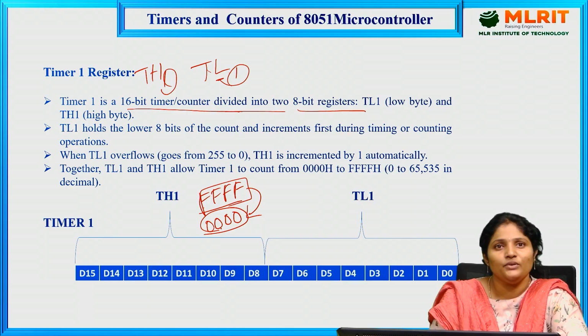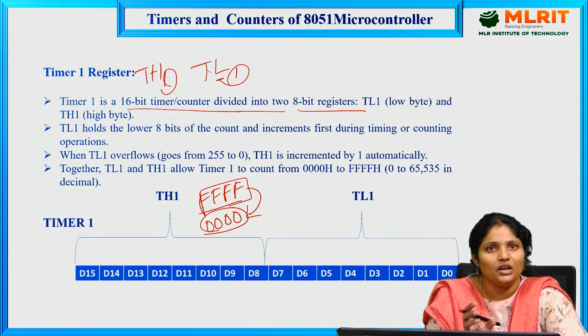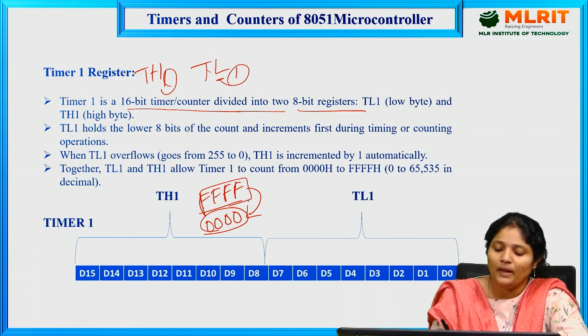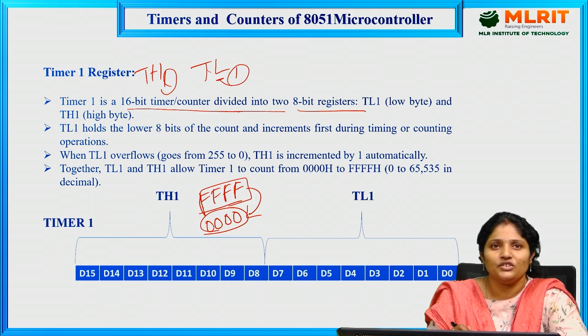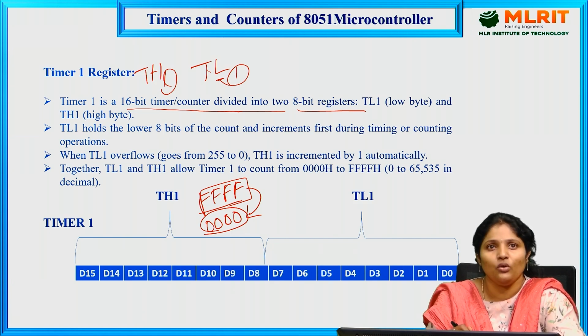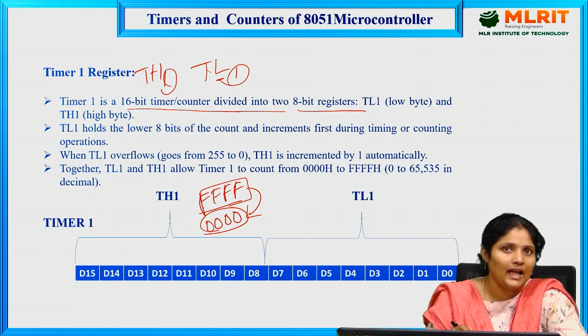When we are using counters also, if a 10-bit counter is there, it will count until 10, then next it will get back to the 0th location, the 0th count. Likewise, if it rolls back to the minimum value of that particular register, this is known as overflow. So how do we check the timers? We will always check the overflow bit. If that timer overflowed, the delay already happened, or the delay is completed, like that we can say.